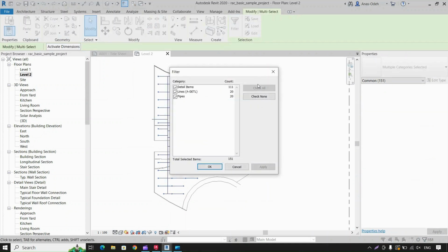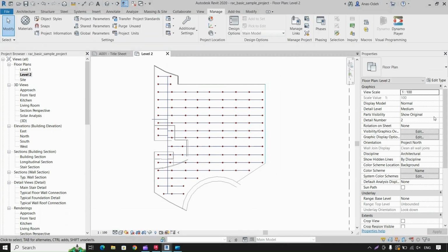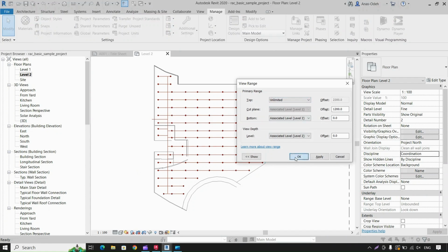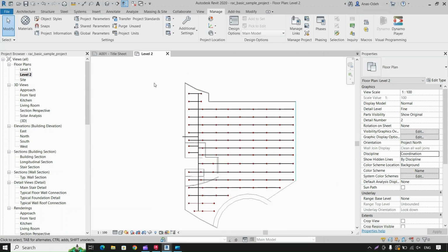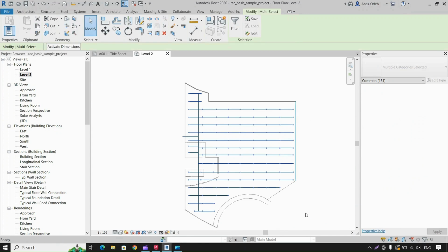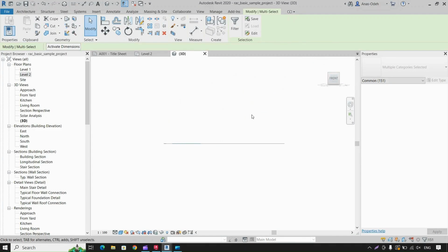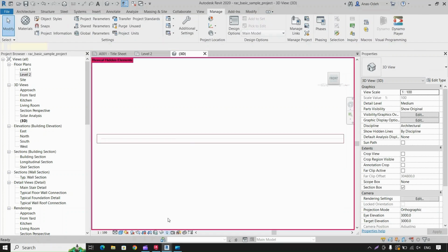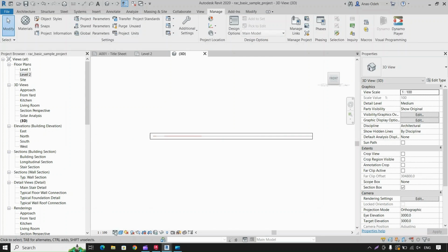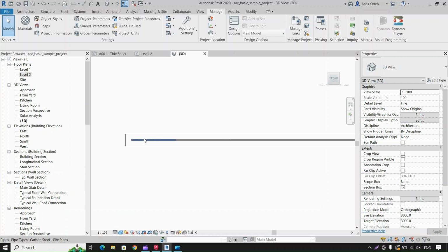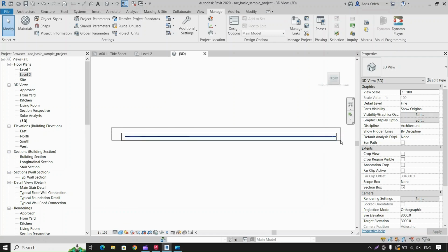Back to Revit. The pipes were added successfully using Dynamo. Change the view settings if the pipes are not visible. You can use this method in similar applications, like converting the AutoCAD imported lines to ducts, electrical conduits, or cable trays. Consider this as an exercise for you. Convert the AutoCAD imported lines to one of the previously mentioned elements in Revit using Dynamo. Then make a user-friendly interface using Dynamo Player.